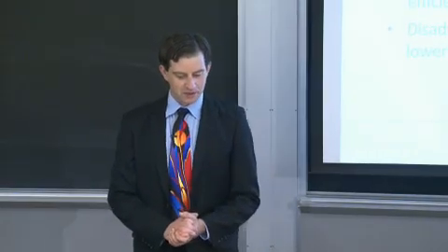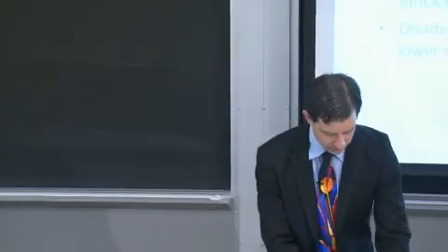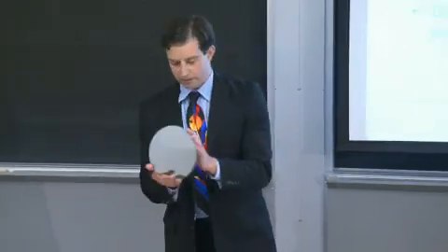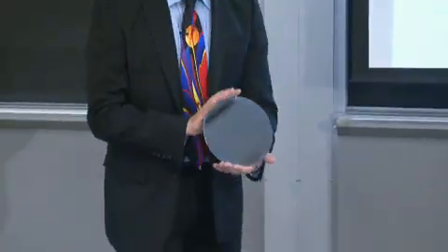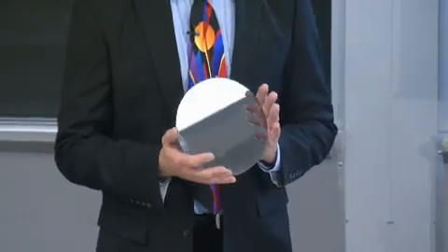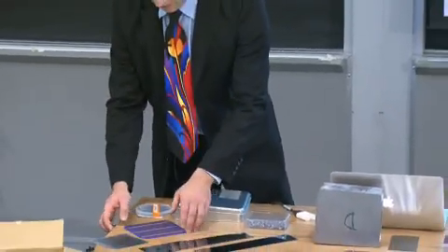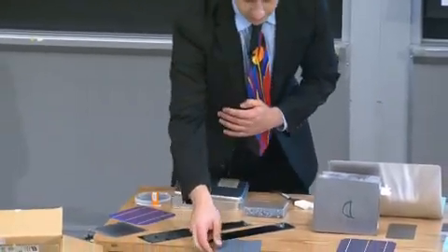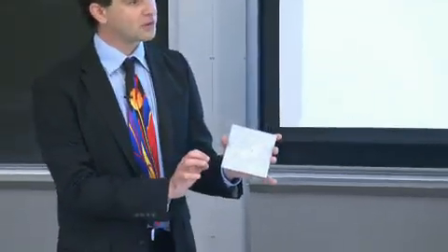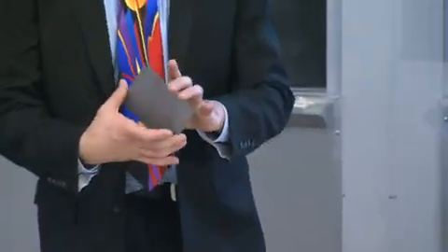and how well controlled it can be as well. During integrated circuit fabrication, which uses this ultra-high purity silicon to produce very nice single crystal wafers like this one right here, the investment per gram of silicon can be on the order of a few tens or even low hundreds of dollars per gram of silicon and still turn a profit. But in a solar cell, on the other hand, you can invest at most a few tens of cents per gram of silicon. This is because the solar cell has to compete against bulk power. That's its competition coming out of the wall right over there. So the solar cell has to be able to be produced much more cheaply. And as a result, typically thinner wafers are used and less expensive starting materials and faster growth methods,